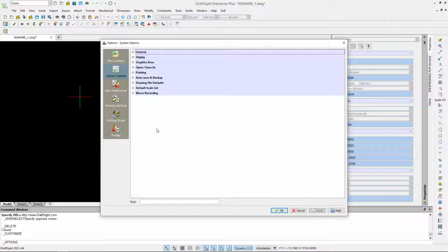And then what's really cool is you can actually have an administrative settings file. That can set up some default overrides. Not all the options are available in the administrative profile or file, but there are some good general overrides that you can do. You can even make that read only, and even if somebody goes in and changes it, the next time they start up DraftSight, it's going to use your company standards files.